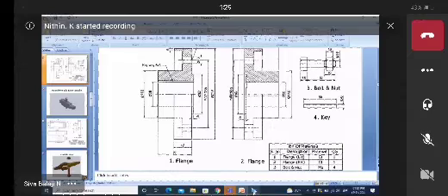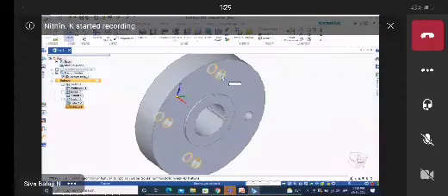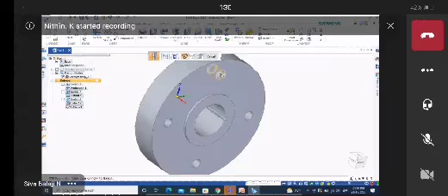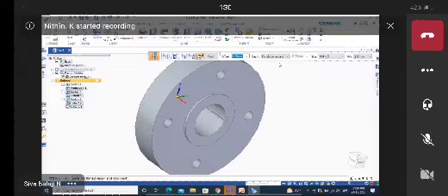Okay, for the nut and flanges you have to make it. If you want to make threading, you can make it here. You can select the hole command. In the hole command you can select the thread command. You can check that standard thread is there. You can take tap drill. Okay, and you can select this feature. Now I want to create threading here, so you can select this one. Okay, now it is asking for the starting point. I selected the starting point here. Blue cylinder. It is asking for a finite value. If you select finite value, you have to give a value. Now throughout the cylinder is required. Throughout whole threading is required, so you can select cylinder extent here.